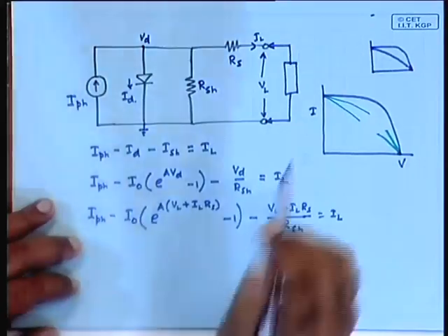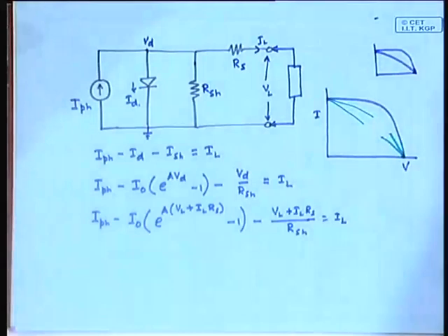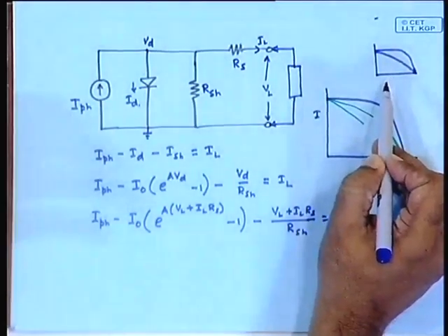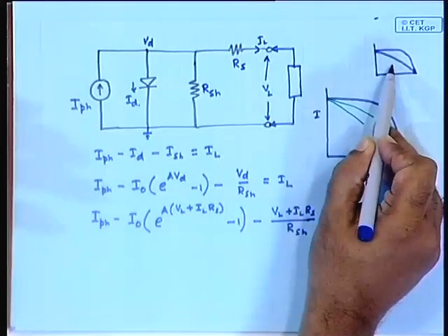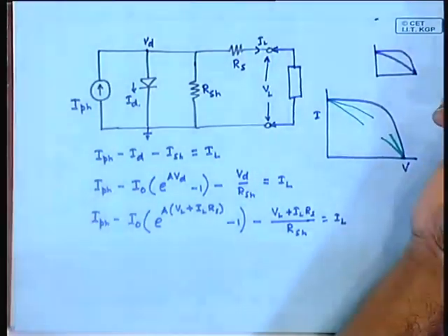Notice the VOC and ISC remain the same, well, almost, yet the power that you can get out of it goes down because the fill factor goes down. So, if you now still specify it, you will say that it still produces the same open circuit voltage, and often people do not understand this. If you measure it, the voltage is still the same, yet the cell is not now as productive, and this is also true for badly manufactured panels.